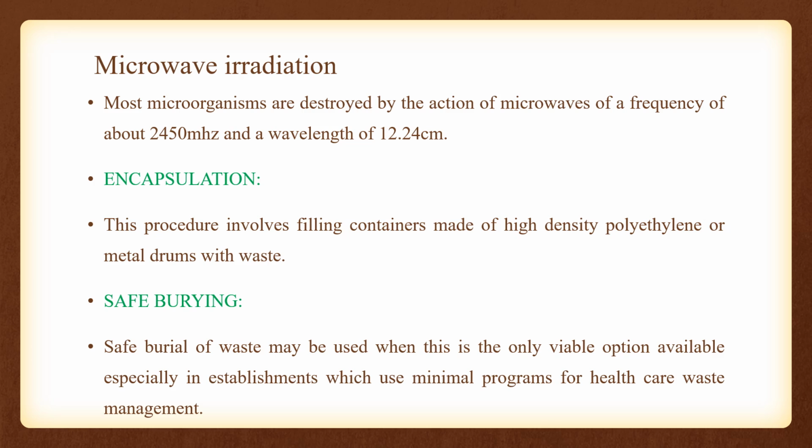The fourth one is microwave irradiation. Most microorganisms are destroyed by the action of microwaves with a frequency of 2450 MHz and a wavelength of 12.24 centimeters. The water contained within the waste is rapidly heated by the microwaves, and the infectious components are destroyed by heat conduction. Although this process is becoming increasingly popular, relatively high costs coupled with potential operation and maintenance problems mean that it is not yet recommended in developing countries.